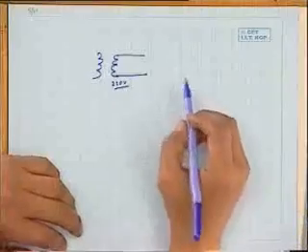Therefore, the decision that the transformer should have X equal to 1 is to be deeply considered. In the peak hours, the loading will perhaps be rated. Are you getting? So, taking all these things into account, it is not always true that X equal to 1. Of course, if you know a transformer whose loading on the secondary side will practically remain at its rated condition round the clock, then go for X equal to 1.